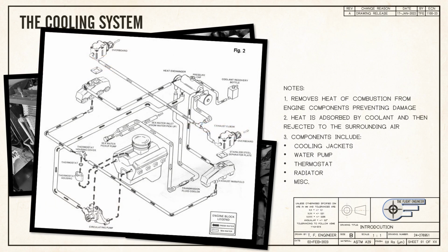In some applications, typically marine ones, the radiator is replaced with a heat exchanger. This allows for water glycol coolant to transfer its heat to seawater pulled from outside the vessel. The heat exchanger allows for the two fluids to transfer heat without actually mixing.